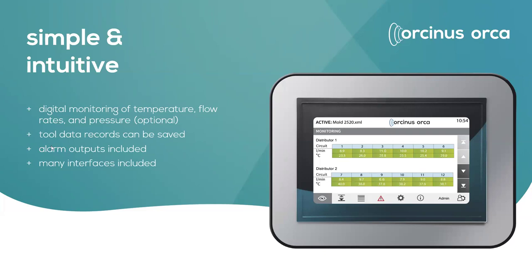So the alarm outputs give you the situation: if one of these terms turns red, then you will have an alarm output to the injection mold machine and the machine will stop, because anything you produce from now on would not be in perfect quality. So this gives you an insurance to always have perfect quality.